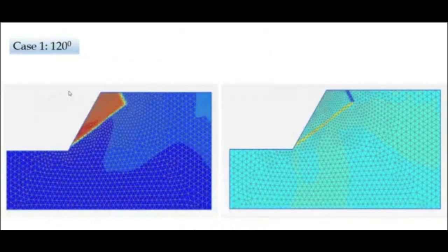Now, what is interesting to note is that for the same strength parameters of the joint sets, I just changed the orientation of the joint sets. Now you see that the failure mechanisms have changed. You will see an inclined straight line and one more line cutting across it in a perpendicular direction. This is the displacement plot on the left hand side, and on the right hand side you have the strain plots. So you can see that there are two distinct failure planes.